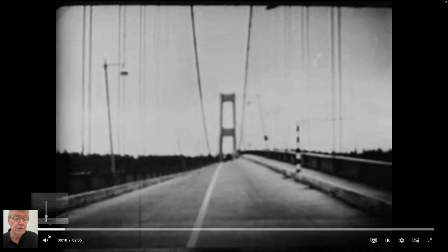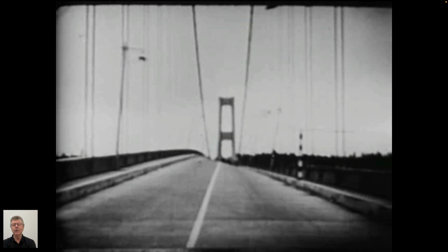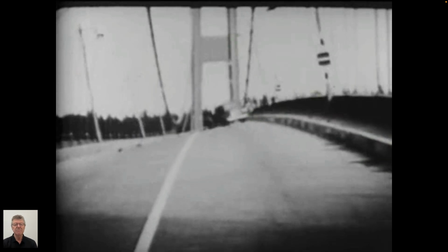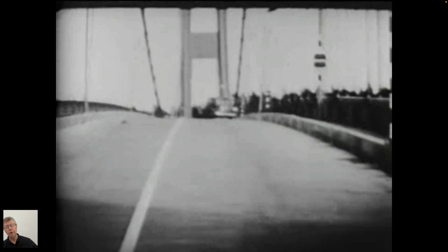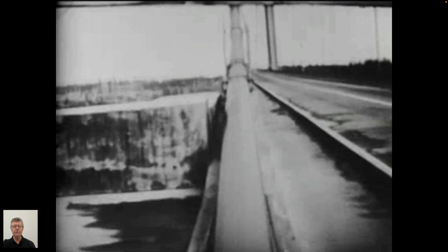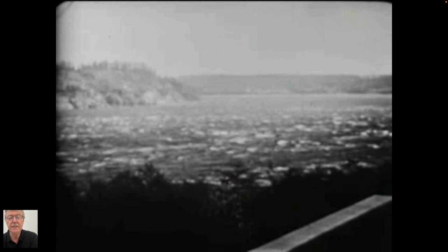So, Galloping Gertie, right? You've seen this before, must have seen this in high school physics classes. Again, it's an external flow, and we've talked about the reason for it before: wind blowing above and below the deck acts a bit, not so much like an airfoil, but on the trailing edge, if it's blowing from left to right, on the right-hand side, you get these vortices shed successively from the top deck and the bottom deck, the so-called von Karman vortex street, that plucks the bridge at each exiting vortex.